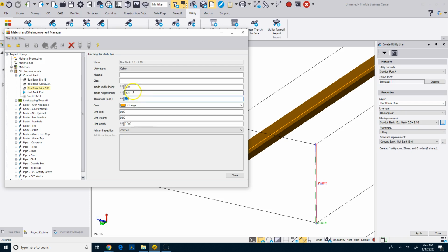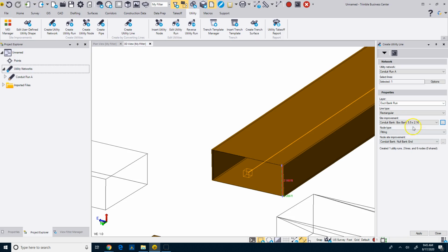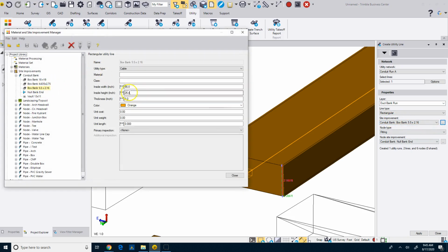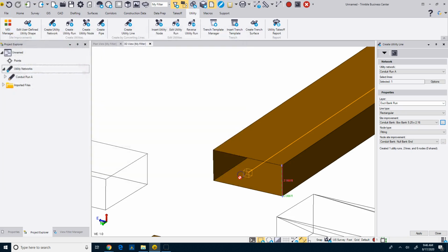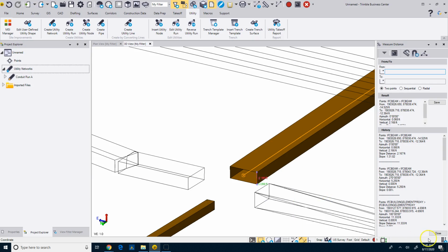So by putting the foot symbol in, it converts it. Now when I hit close, you'll see it makes that proper size. I think that one should have been 5.25 feet too, and let's rename it. So I right click over here and I'm going to do 2.5. Again, I wanted to show you that in case you make a mistake, it's pretty easy to correct your mistake.